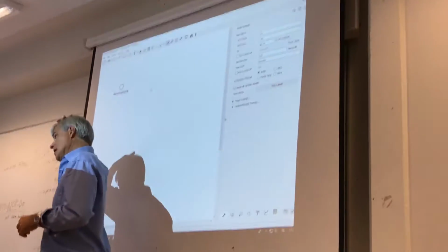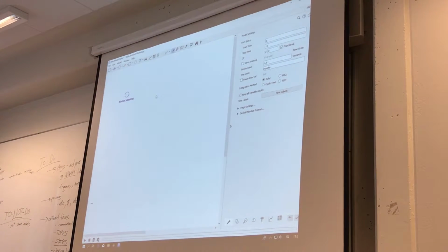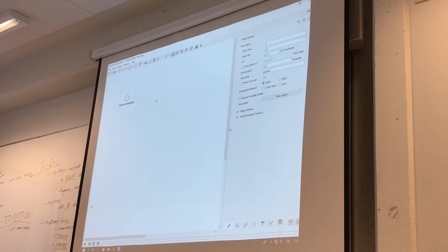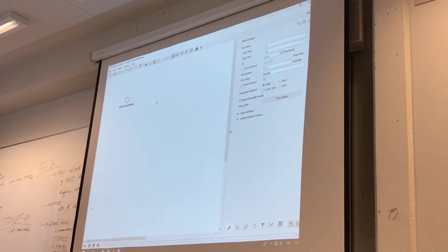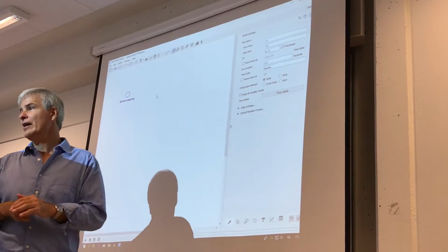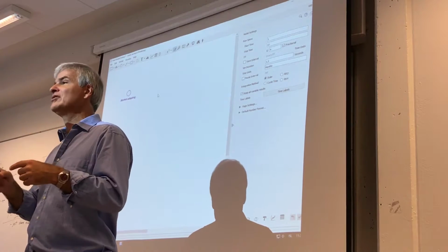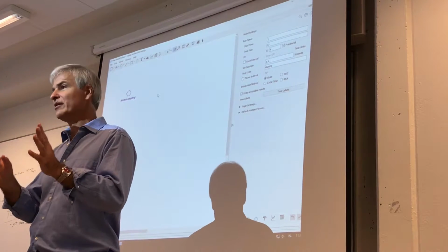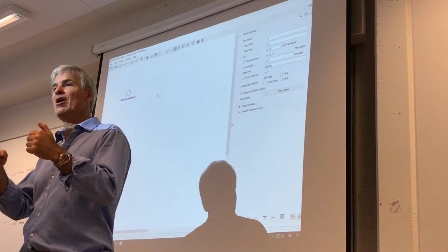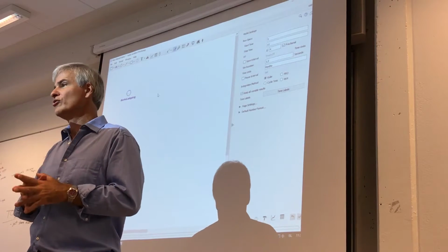Okay? Now, I lost the part of copying. It is not cut and paste, copy and paste. I use the ghost tool. Ghost, click on one. And then I go up and across. So the biggest problem that people run into using this is they accidentally click somewhere else on the way. And they don't end up inside the module where they want to go. And that's why I said let's go very slowly, especially if the name of the thing is inside the module, they end up double clicking on the name. And then they lose the ghost tool.